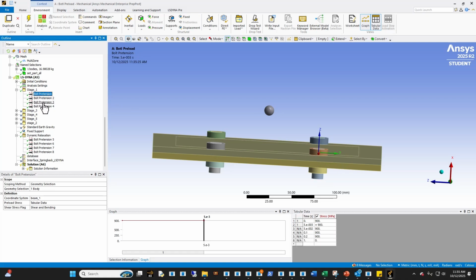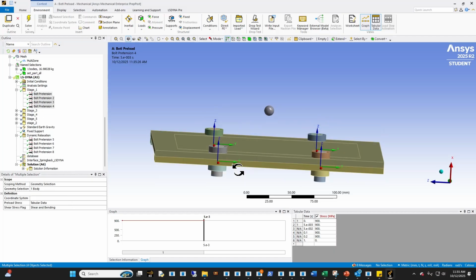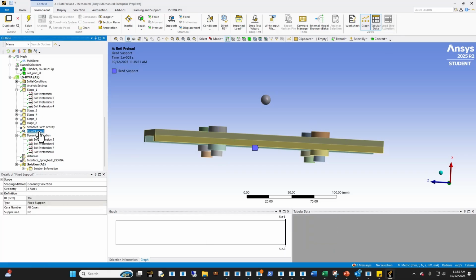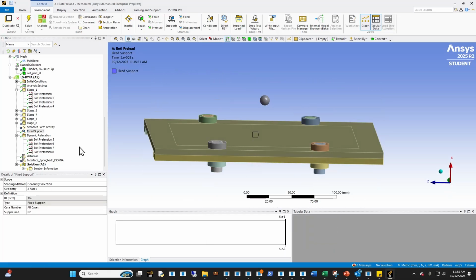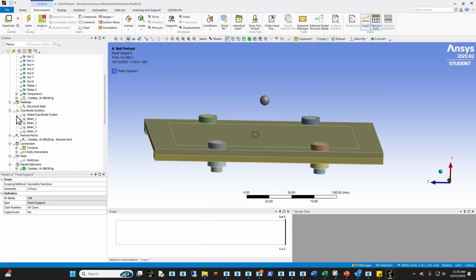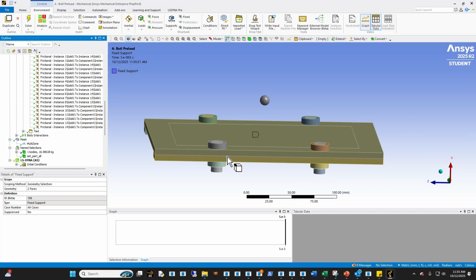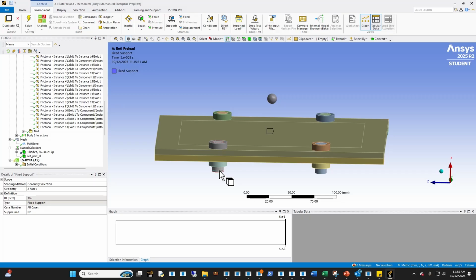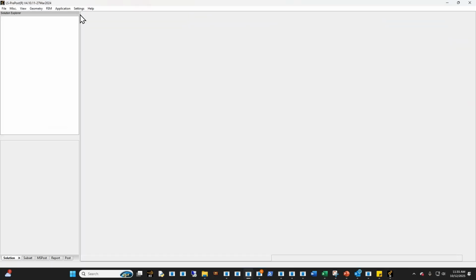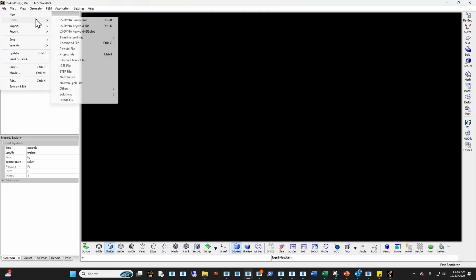Now you can also do this during the transient analysis. So these 4 right here will actually account for the transient analysis, right? Everything else is basically just a fixed support on there, and then that's pretty much it. There's not a lot to it. I won't go into the little contact detail, but basically you can sort of imagine you're just bolting things together. The bolts are tied to the nuts, and everything else is frictional contact.